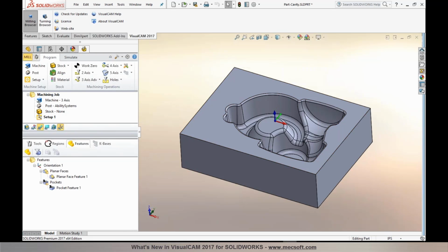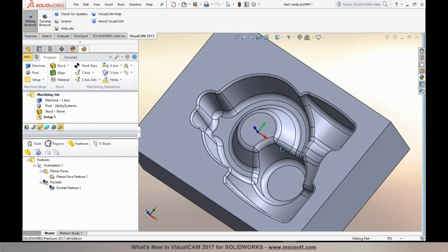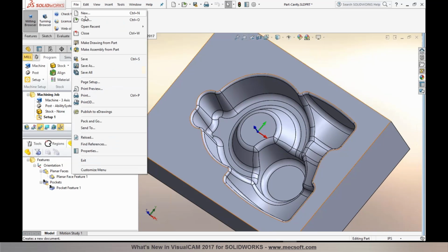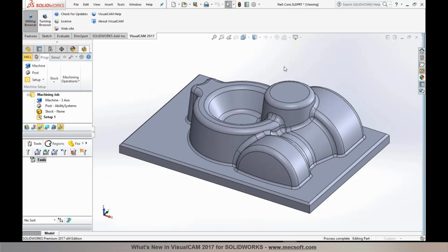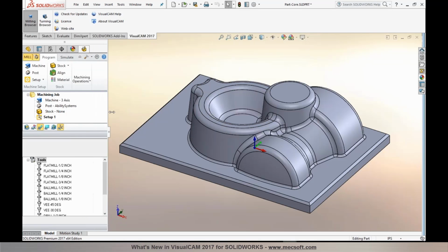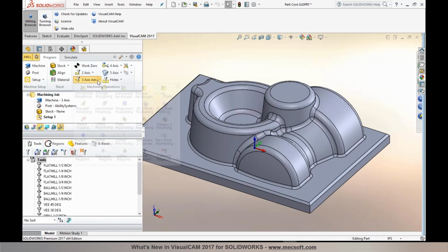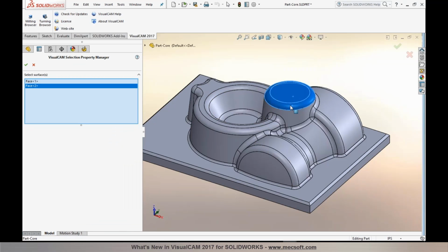I want to interrupt a bit here and go back to your surface selection, and I wanted to emphasize one little feature of the surface selection function that we just added. When we use the surface selection and do machining, the cutter actually checks against all the other surfaces around it, so there's no danger of gouging the other surfaces. So that's an important point that we have to emphasize here. Do you have an example that you can show for that?